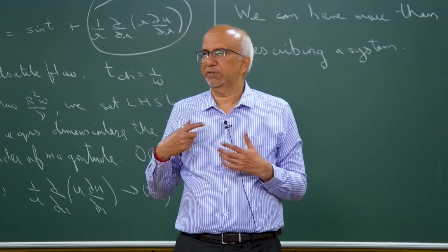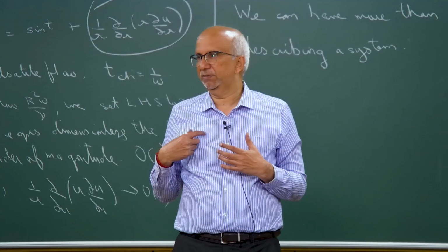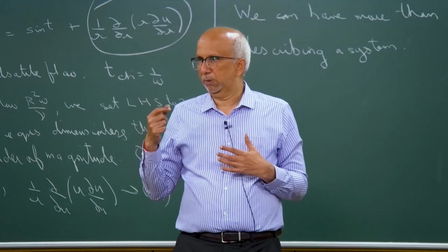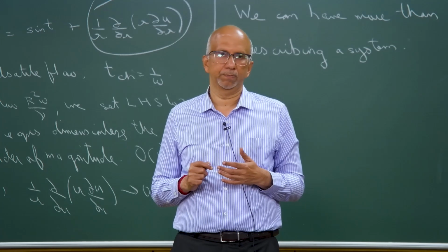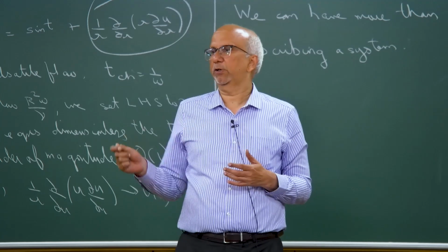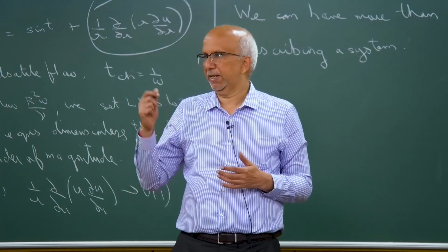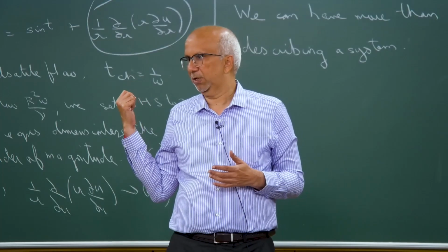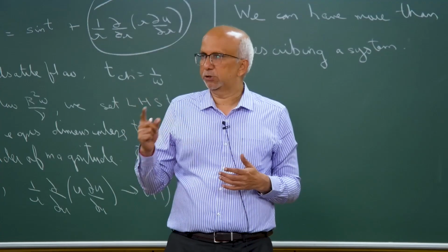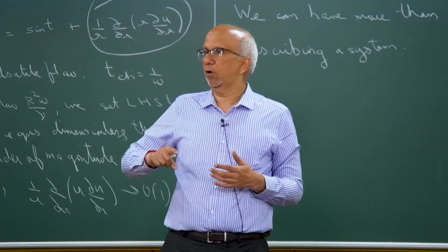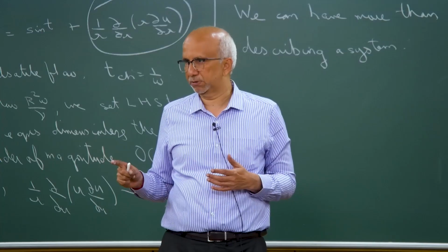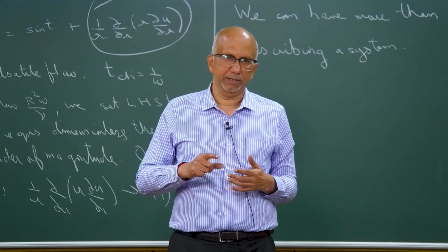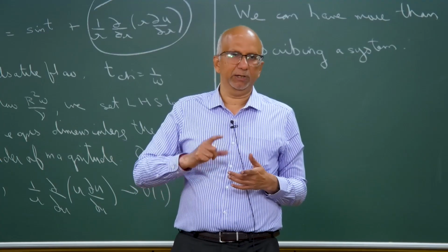Suppose the experimental parameter within your control in this problem is the frequency of the input, and you want to study the effect of frequency. Frequency right now occurs in my Strouhal number. You have to ensure that the frequency does not occur in any of the other dimensionless numbers, because only then does changing frequency affect only the Strouhal number.